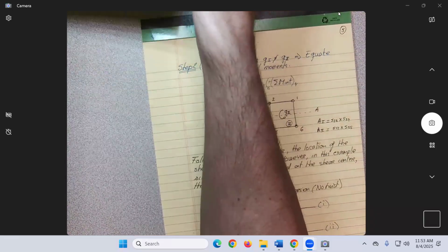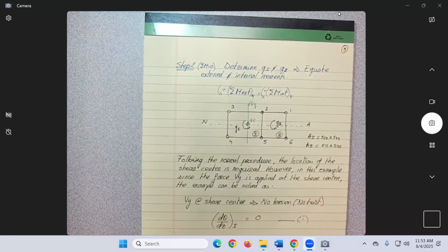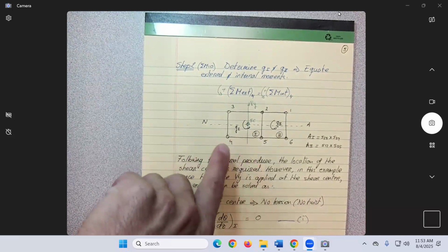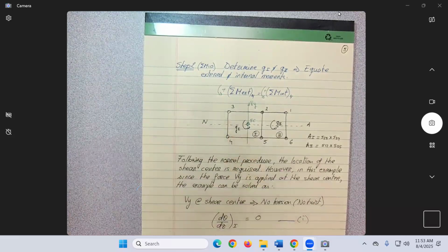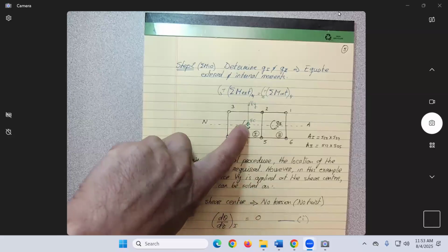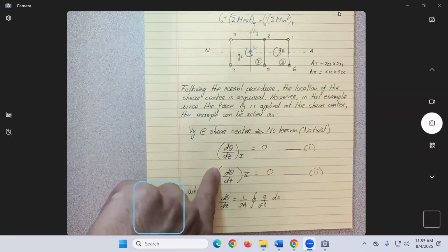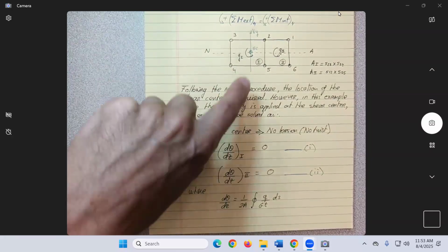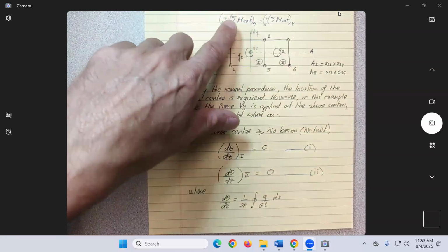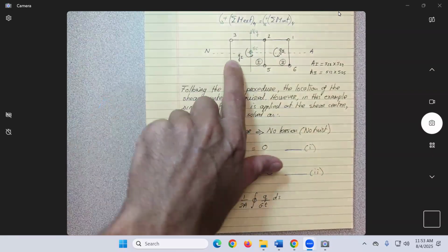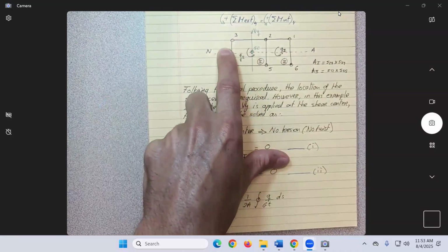Yes. So if the force doesn't go through the shear center, you can apply this. If you know the location, yes, then you need to use the normal procedure, because you will know where the force is applied. You could also solve this problem by first finding the position of the shear center. But how would you find it? Doing exactly the same thing, but your unknowns will be, as we did, dy and dz, will be Vz and that distance here. Okay.